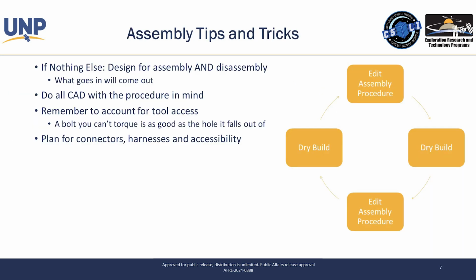At this point, where I think most of you are in your CubeSat journey, you have to plan. The whole exercise of decomposing all of your requirements and saying, I'm going to do this as a 3U CubeSat. Everything needs to be planned to fit into that 3U volume when you actually assemble it. You can't have a 3.25U where you decide, well, I'll just kind of lump something here on the side because it didn't actually fit in the end of the day.